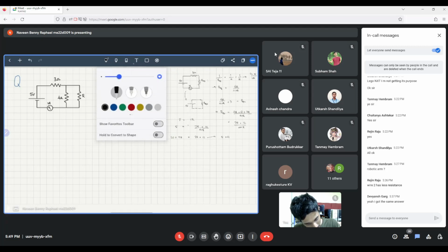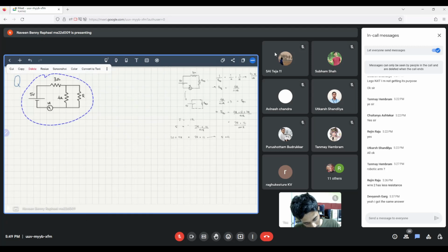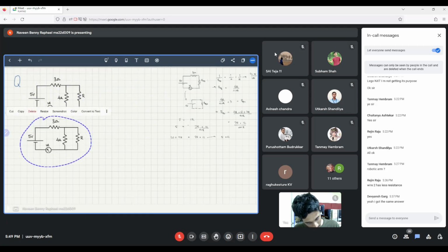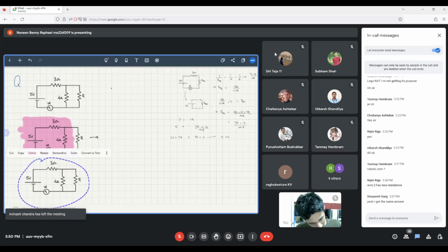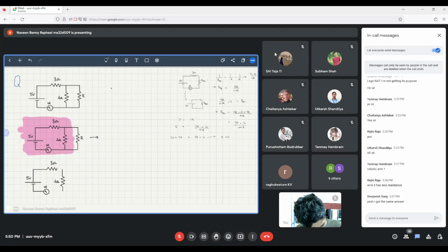Let us consider, okay, let's find the Thevenin equivalent of this part, which shouldn't be too difficult. If you find the Thevenin equivalent of this, this entire thing becomes V Thevenin, R Thevenin, joined with R and here.